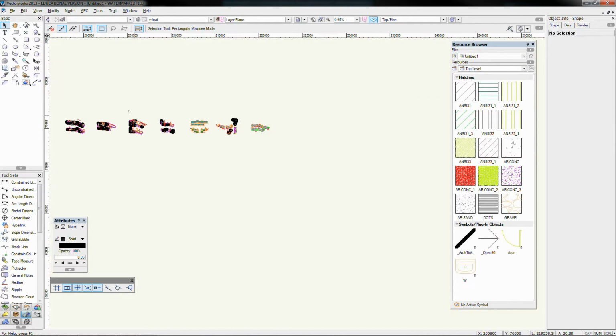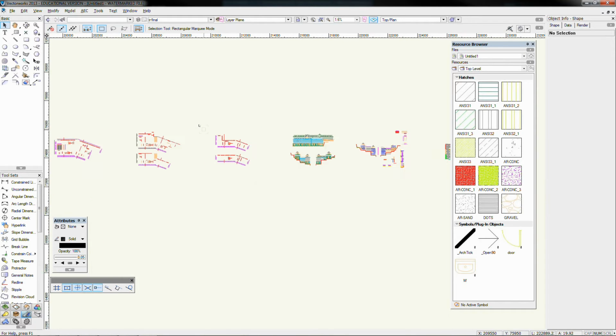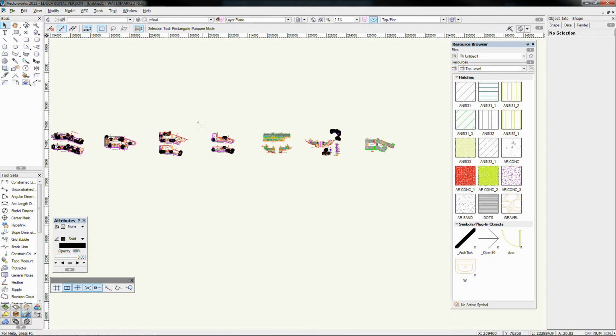So the next step that I would normally do here is just make sure my dimensions were correct. To do that, just to speed up my document, I'm actually going to select all with my Control A, or Apple A for you guys on a Macintosh. You'll see it'll take a moment to think about that, and probably up here it's going to be a ludicrous amount of objects. There you go, almost 100,000 objects. Just to simplify this, I'm only going to keep one component of this.